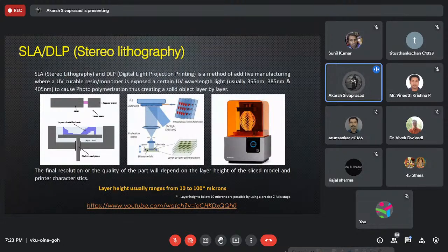So you need to do a lot of cleaning after that to dry your part, and then put it through a second post curing to cross-link it even more and make it harder to the final exact material properties that you want. It's not that common, but I've seen this technology moving into the common household as well in the near future.